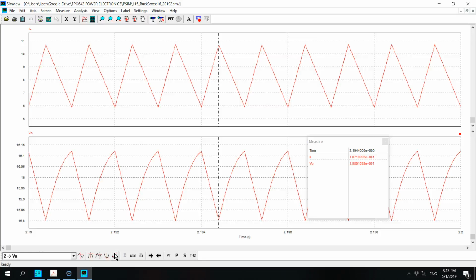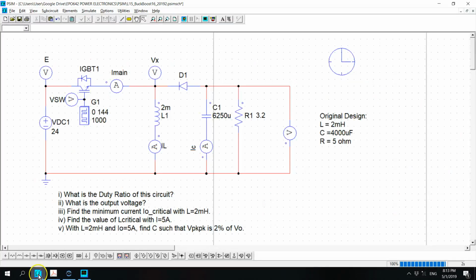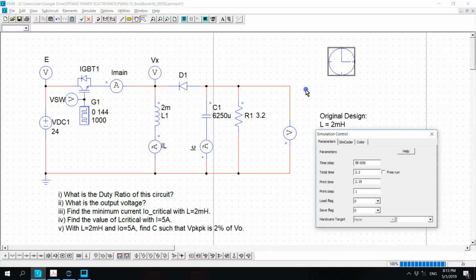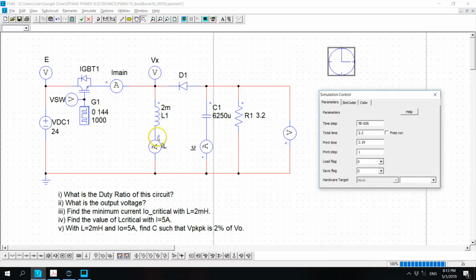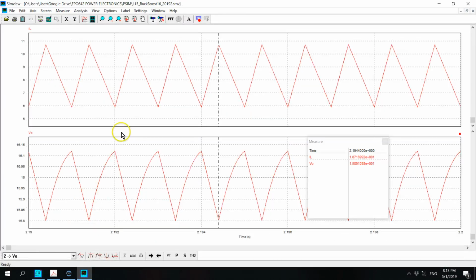So it's quite accurate if you use simulation, and therefore the simulation will help you to confirm your calculations. But again and again, you need to simulate it properly so that you get a correct waveform. When the waveform gets into a steady state, you can see that it is symmetrical. The inductor current is symmetrical, the output current is symmetrical.